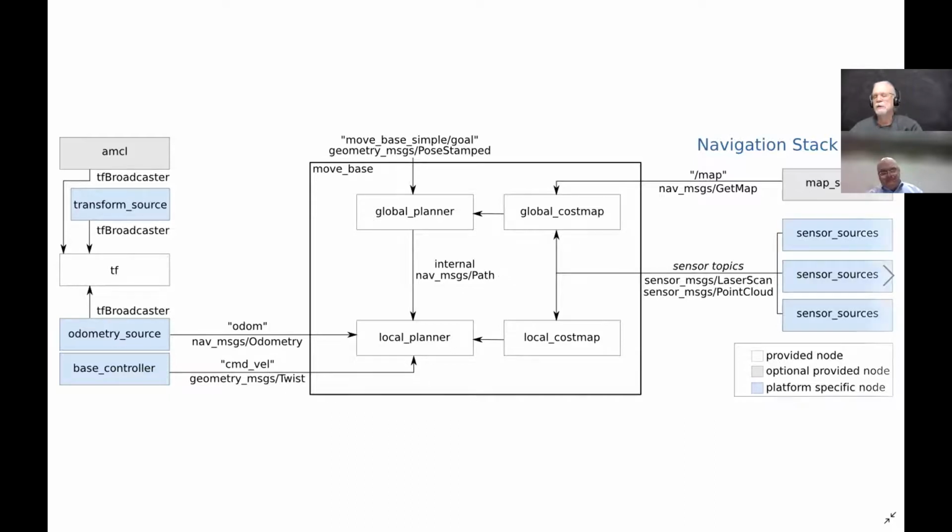And other things on this, again, the map server. Typically, if you're driving inside of a building, instead of starting up AMCL, you start up one of the SLAM programs, which is simultaneous localization and mapping. What that does, you start it up with a blank map, and then it takes your observation sources, and mine has a laser scan on.